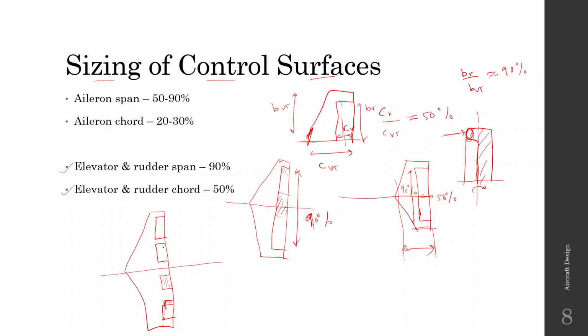These flaps are used to increase the CL max during takeoff and landing. And it is desirable that the flaps do not produce a lot of torque. That is why this location is appropriate, because since they're close to the center line, even if there is some imbalance, it will not produce a lot of torque.